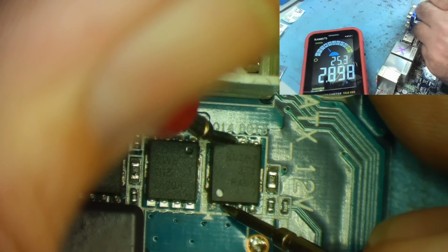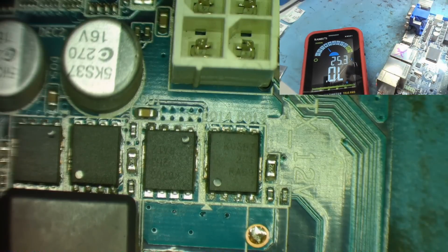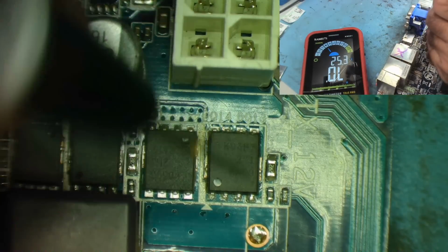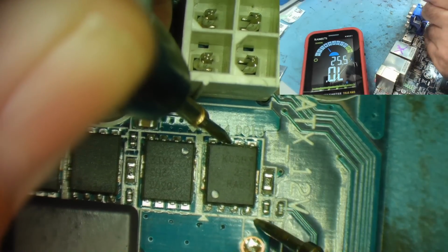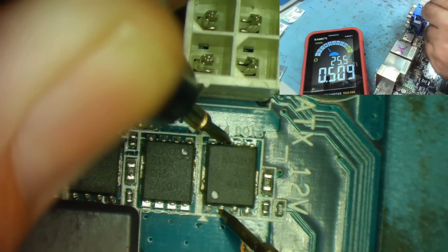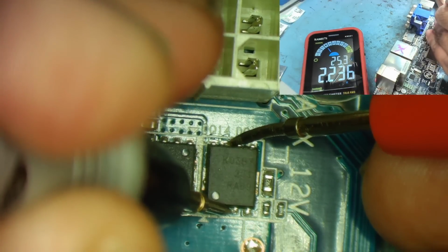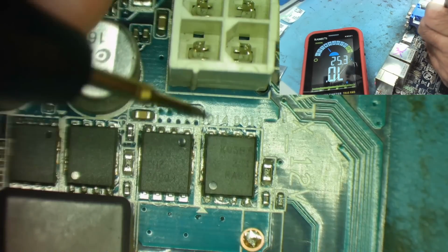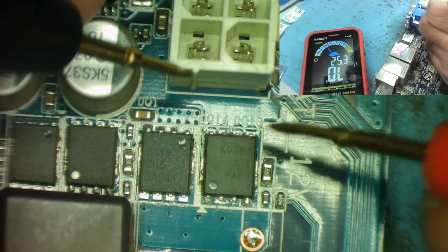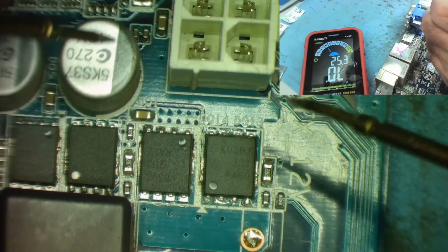I'm reading some resistance, but bear in mind there's other components in the circuit. And if I go onto the gate, which is here, and then back onto the MOSFET, I should not be able to turn it on. We have the diode junction. Okay, and a little bit of resistance the other way. So this is what I'm saying, you should not be able to turn them on like I was doing out of circuit. If you can, you've got a problem.